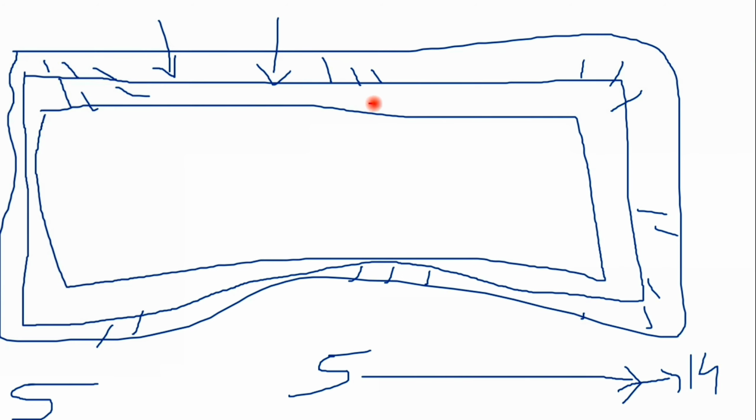Again, I install the Wellpoint system. Now, the second stage also lowers the water table by up to 5 meters. Then right now, what is my actual length in terms of depth? 10 meters. Again, the same question: up to how much depth do I need to go? 14 meters. So again, you want to provide one more stage.